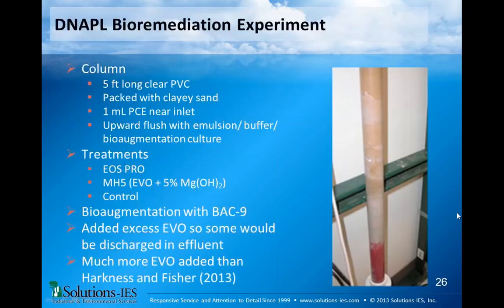Okay. So what's the best way to calculate the volume of buffer that needs to be applied? We do it in a process of steps. Calculate the amount of acidity that's going to flow in from up gradient. Calculate the acidity associated with the soil. Calculate the acidity associated with the hydrochloric acid you're going to produce during the bioremediation process. And also calculate the acidity associated with the CO2 you're going to produce during the bioremediation process. Add them all together, and that's the amount of buffer you have to add.